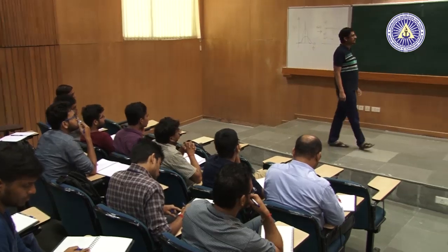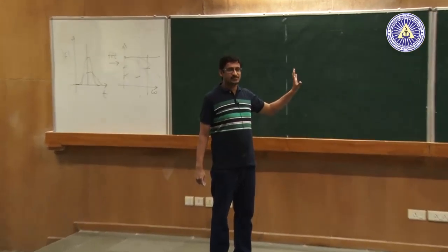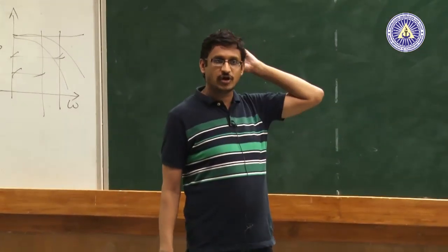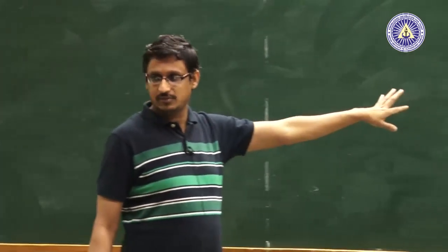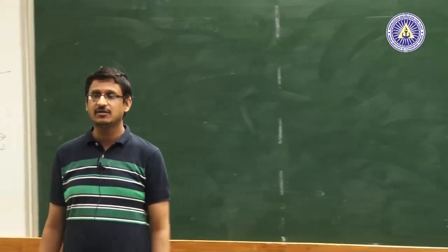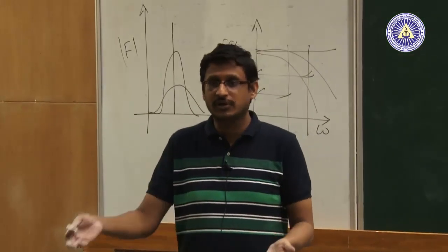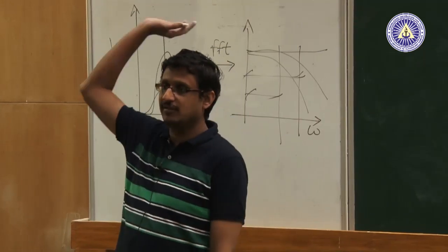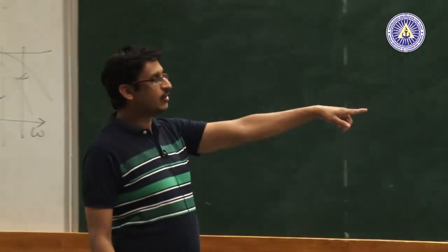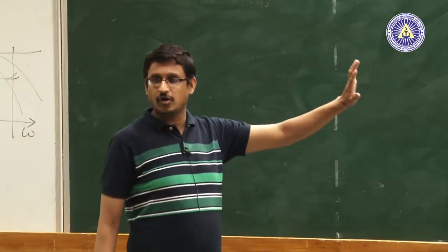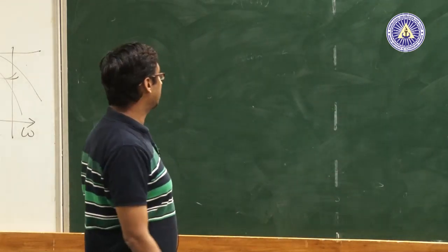So appending zeros is for a different reason. In discrete time signal processing, appending zeros has its own place, but that is in what is called evaluating convolution. There it is okay, but not in this particular case. So physically, you don't gain any new information by adding zeros. When you have to add zeros, why stop at only m? You can keep adding zeros all the way, but you don't generate new information, right. That problem is called spectral loss, sometimes called scalloping loss, or spectral leakage. So that's a very important aspect of the DFT that you should remember.